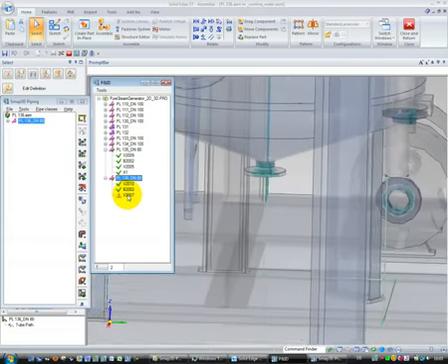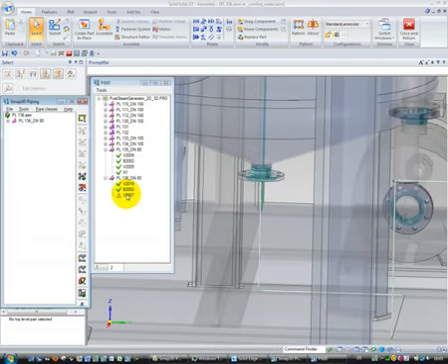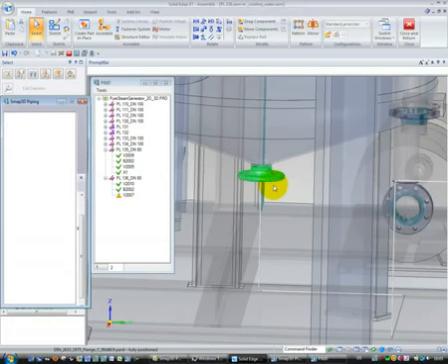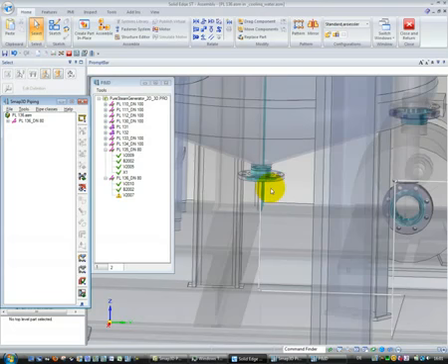For example, if I use the automatic generation before I place a valve on the position, then in addition to this flange of the vessel we automatically get a flange again. But if my valve should be placed directly on this vessel flange, then it makes no sense to generate the pipeline before, delete the flange and then update the pipeline.